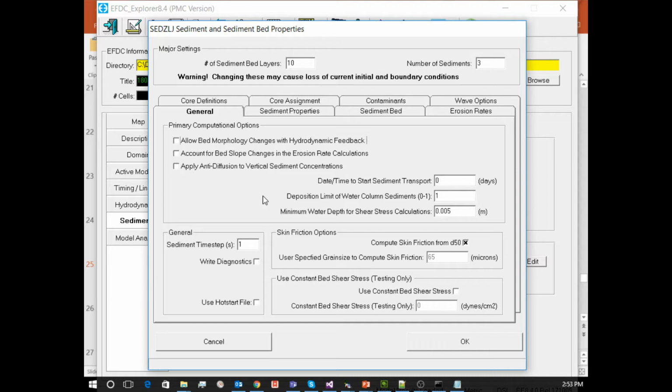And that is a nice way to pick, oh, well, I can be up to 20 times before I see any kind of significant difference. But there will be a difference. The same thing applies to water quality and toxics and all of them. The question is, is it significant? Given all the other tuning parameters, if you can get the model to run faster, and that's always the goal, get the model to run faster and end up with a good calibrated model, why not do it? You don't have to keep the one-to-one correlation. I mean, as we were talking about this morning, coupled models,